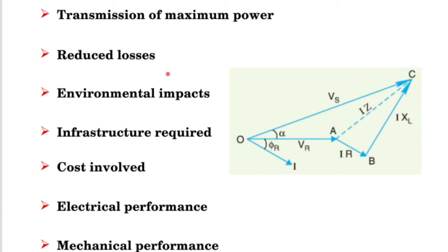But again, if we increase the cross-sectional area, if we remember, that is why we were discussing Kelvin's economy law, if we increase the cross-sectional area of the conductor too much, then what will happen? Resistance will decrease, power loss will decrease, but the cost of the conductor will be too much. And the interest and depreciation on the cost of the conductor will be high, and who will be paying for those costs is the consumers, meaning each and every one of us.